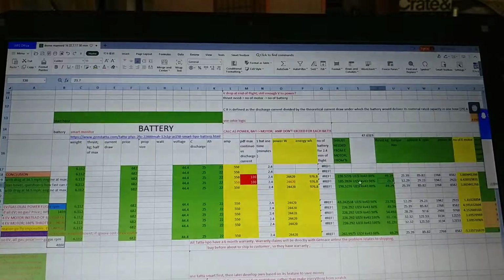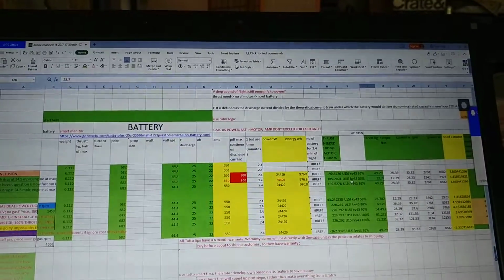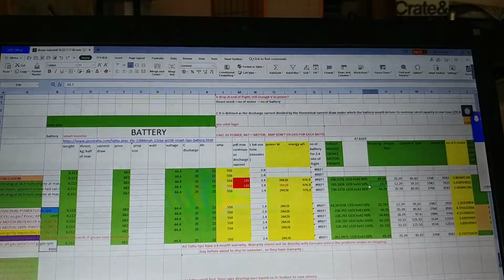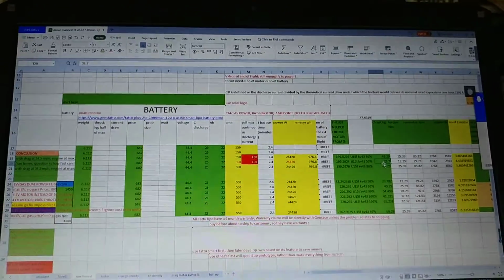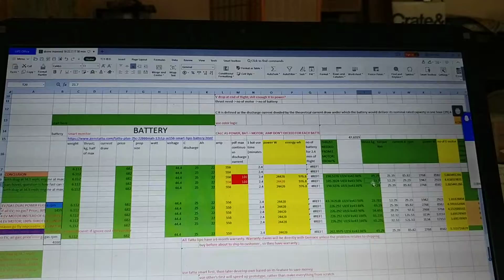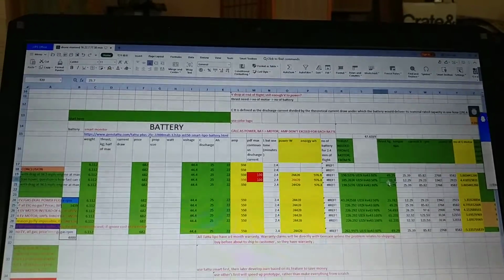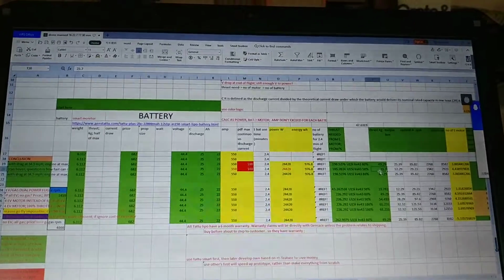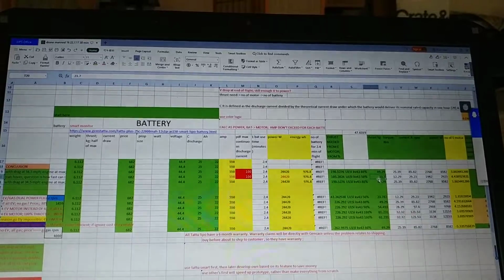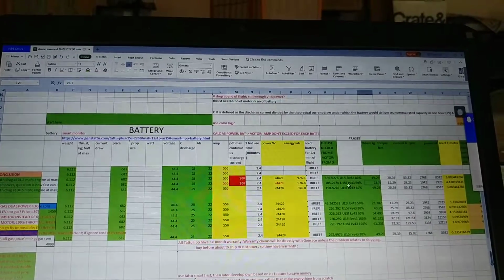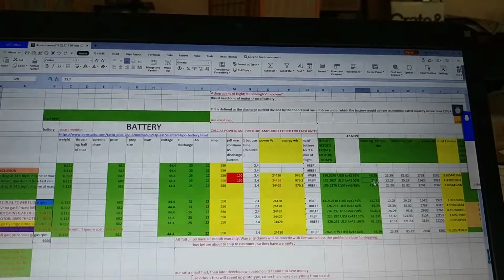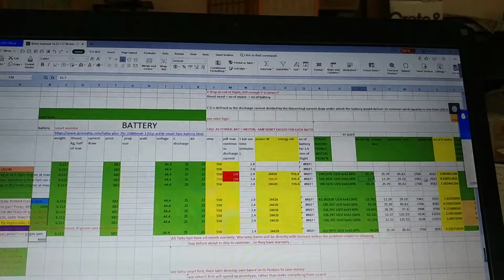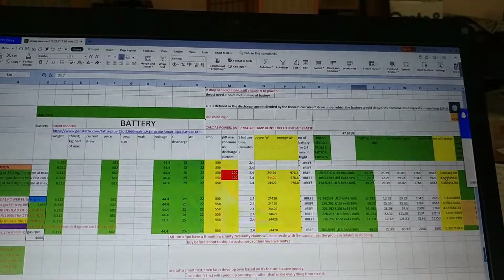And after I know the battery, I pick a motor based on the data, how much thrust it can achieve, and the propeller size, which is modeled in the CAD to make sure it fits in the size restriction. And by estimating the total weight of the craft, I know how much thrust each motor needs to generate. So the first thing is to see if it's enough.